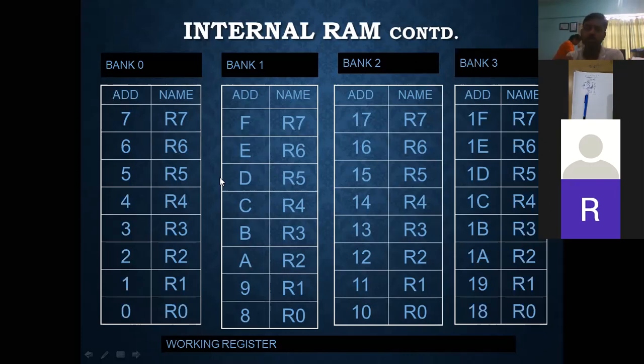But whenever we are using some power sources other than a battery, like a power adapter, just like our mobile phone charger, if we connect those power supplies in place of this battery, then some small signal AC components will charge this capacitor, but the charge is not that much that it will discharge through this RST pin.